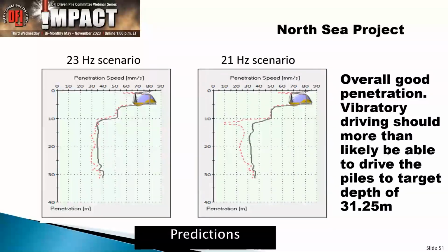Do you have any static load test comparisons to these vibratory installation conditions? We have some, but not as many, because for the larger piles where we're interested in offshore, you don't do static load tests. Let's face it, dynamic load testing was developed in the 1970s, at least in Europe, to start testing piles offshore with the oil and gas industry.